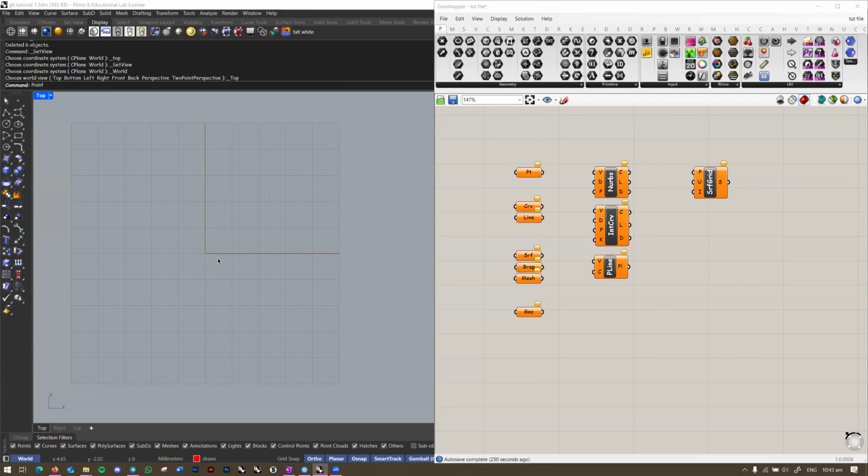So in Rhino, let's create a set of points. For example, usually if you want to draw a curve in Rhino, you go control point curve, and then you draw a curve by clicking on the workspace to create points that constrain this curve. For example, I clicked over here now. So that point there is now constraining this curve. It doesn't want to deviate because these are NURB curves which originate from a set of points. Now I say I want to make another point down here to constrain it. Now I have this point here constraining the curve.